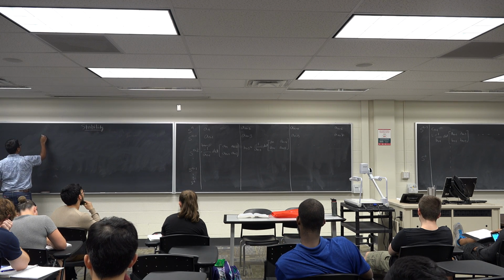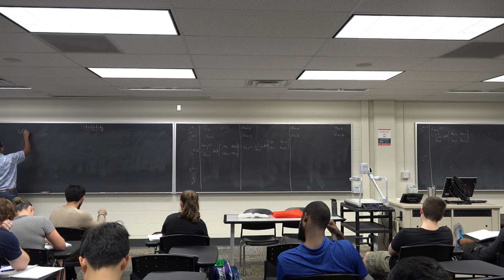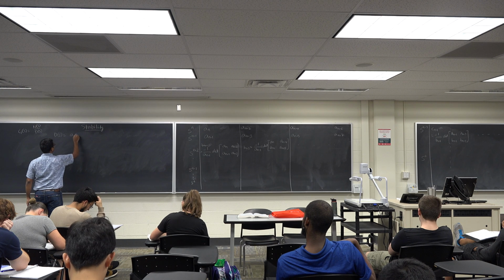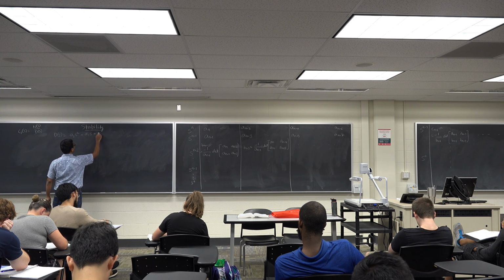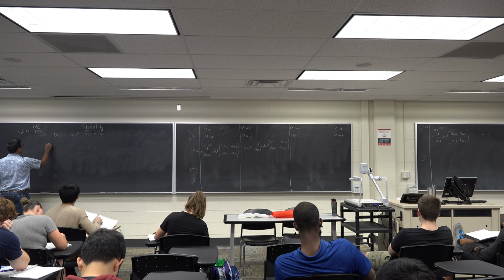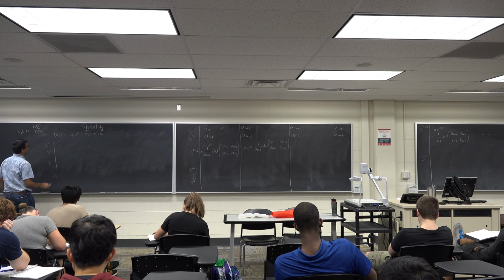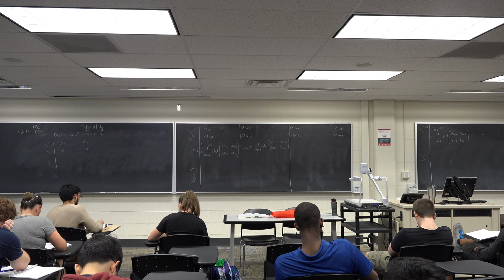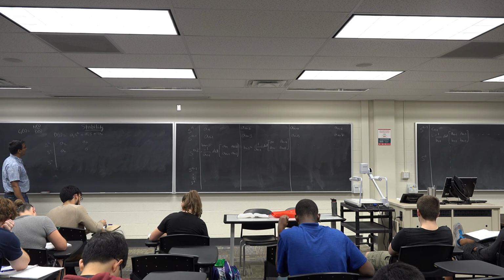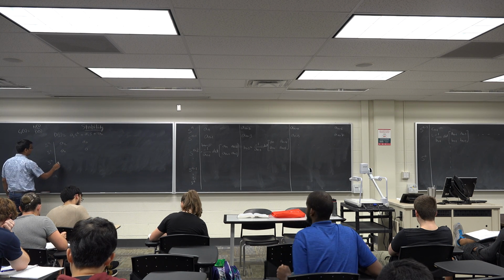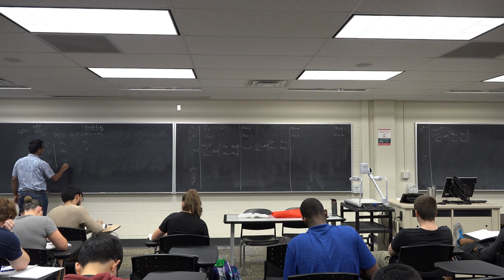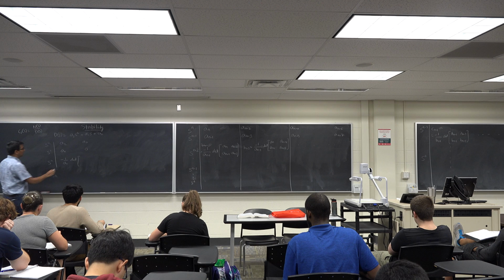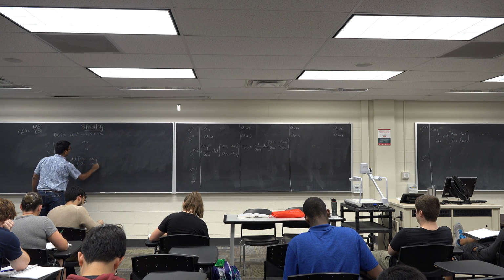So let's say G(s) equals N(s) over D(s), and D(s) is equal to A2 s squared plus A1 s plus A0. So I start with s squared, s raised to 1, s raised to 0. I have A2, A0, A1, and I don't have any term here, so I'm going to write 0 here. What should be the number here? So I have minus 1 over A1 times the determinant of A2, A1, A0, 0.